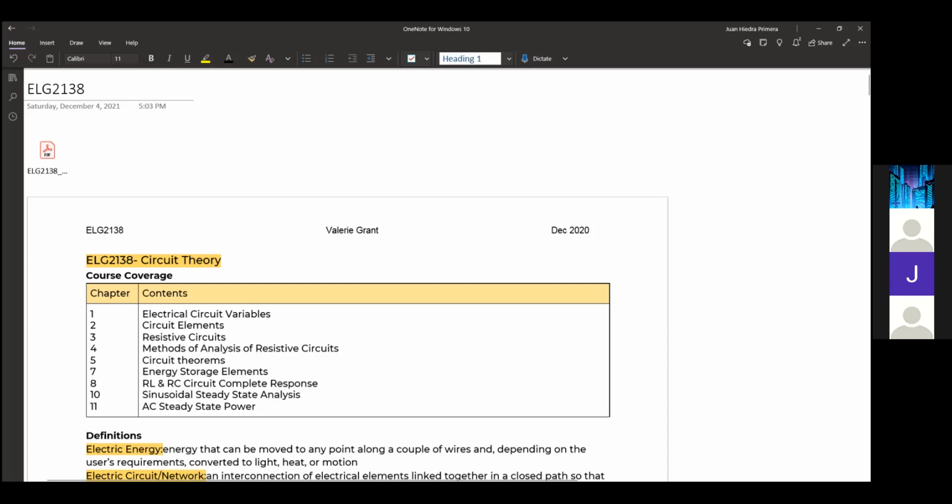In terms of circuit analysis, two important rules to remember are Kirchhoff's current and voltage laws, which are that the sum of all currents through a point are net zero, meaning that everything that comes in must also come out. Otherwise, it's not truly flowing and thus not current. And Kirchhoff's voltage law, meaning that around any loop, you should have a net zero voltage. A good way of thinking about that is that since you measure voltage as the difference between 2 points, if you measure voltage at the same point in a loop, you should get zero. So going all the way around that same circle should also give you zero. Moving on, we have the types of elements, resistors, capacitors, and inductors.